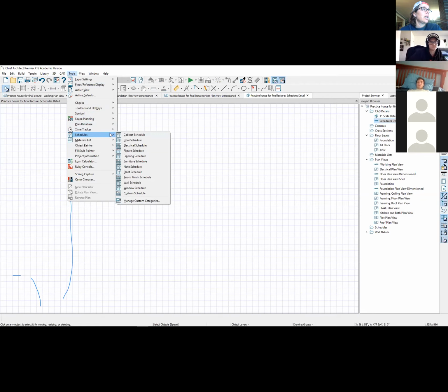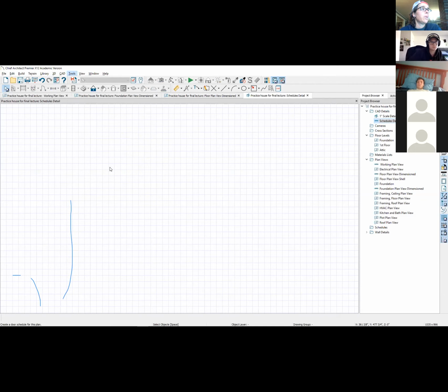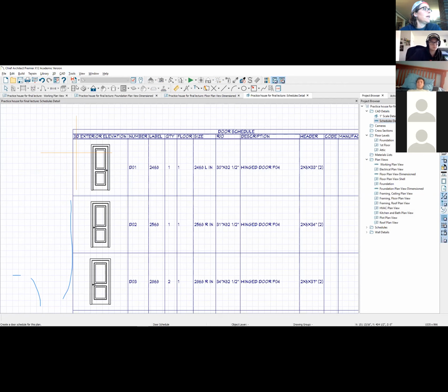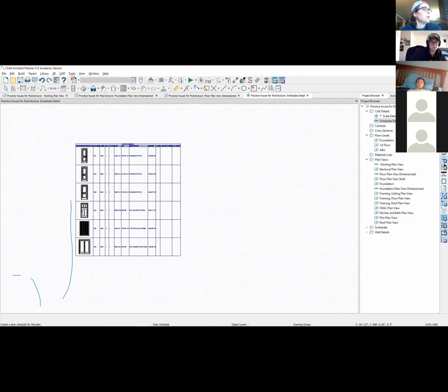The video that you watch talks mostly about cabinet schedules, but we're just doing a door schedule and a window schedule. So I'm gonna place a door schedule. And then I'm also going to place a window schedule here. And as soon as I've placed them, I hit spacebar to get back to my regular cursor. Otherwise it'll just keep placing them.